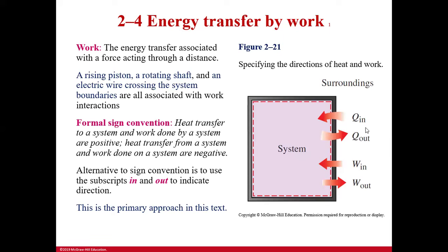What is work? Work is the energy transfer associated with a force acting through a distance. A rising piston, a rotating shaft, and an electrical wire crossing the system boundaries are all associated with work interaction. Formal sign convention: heat transfer to a system and work done by a system are considered positive, whereas heat transfer out from a system and work done on a system are negative.